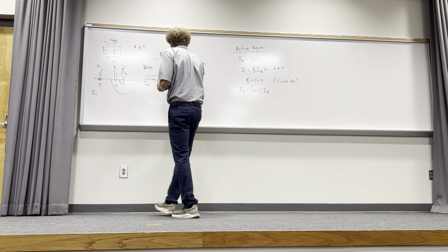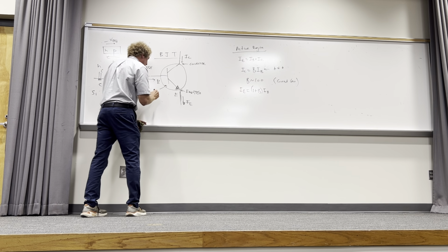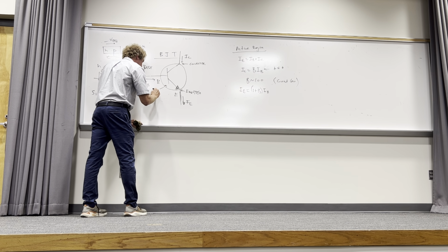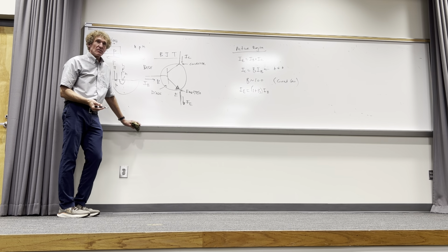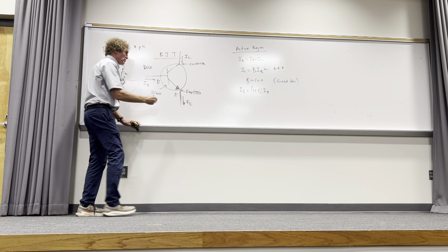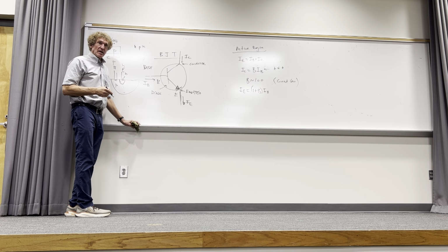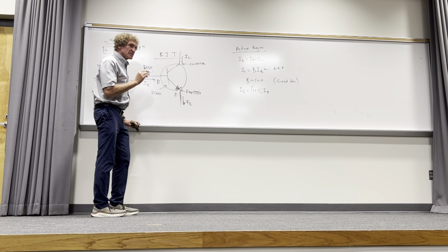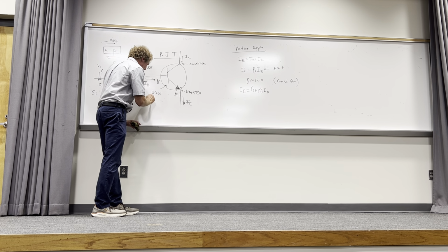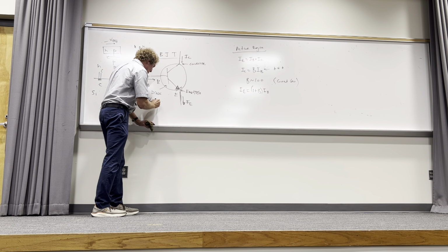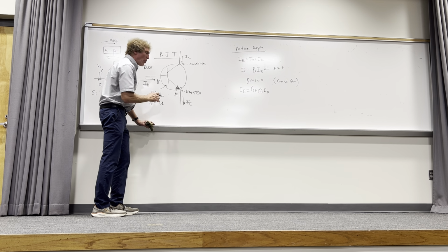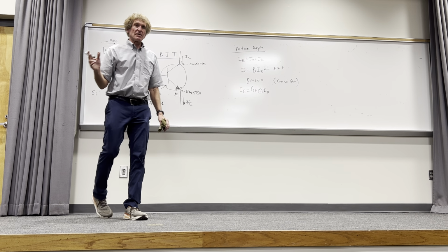And this right here, you might as well think of as a diode. This junction from here to here looks almost like a diode. Follow me? That blocker there. So that's a diode, but it's non-ideal. They'll call it V base to emitter, or V on, or V diode. Don't worry about it. It'll be about 7/10 of a volt, almost always 7/10 of a volt for silicon at room temperature.